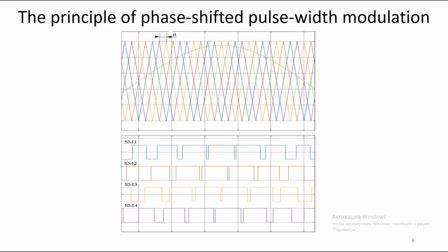However, the arm's value of the circulating current is almost twice as high, 11.8 amperes, which leads to an increase in converter losses. Another significant disadvantage of this method is the loss of the ability to balance the voltage on the capacitors of the modules. The positive effect of using such a system is reducing the total harmonic distortion to 21.71%.